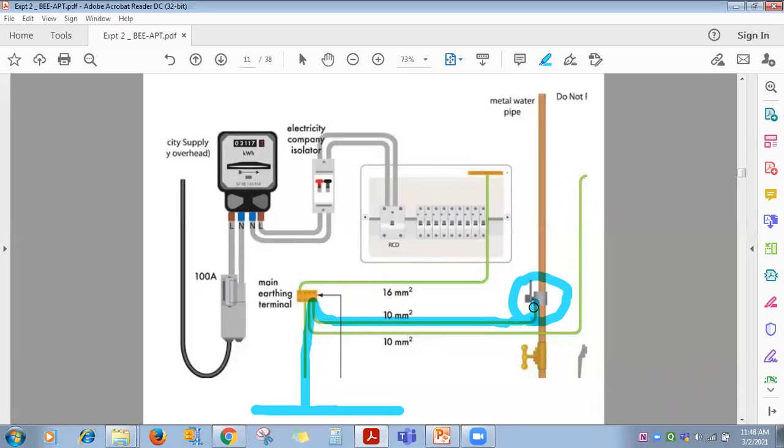So rather than your body, even if you are touching that motor or generator outer metallic body, this leakage current will flow through the earthing wire, whose resistance is less than 5 ohm, to ground. That's why earthing is required. If this earthing connection is somewhere in open condition, suppose here it is broken, then what will happen? You will get shock. So this earthing connection must be proper.